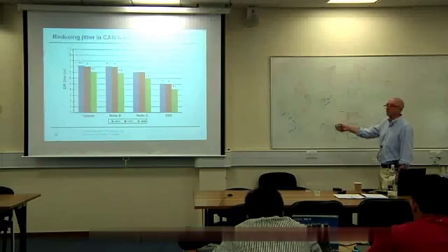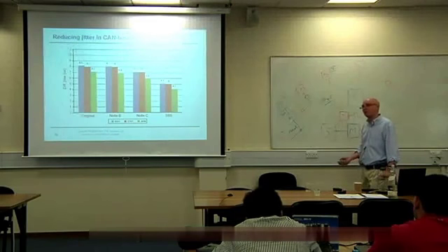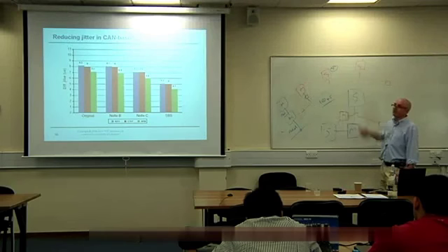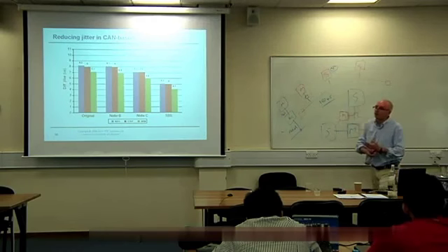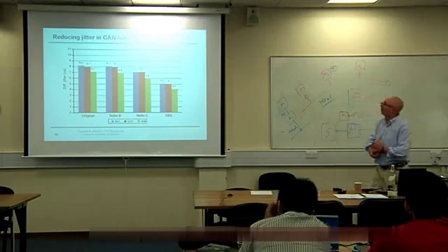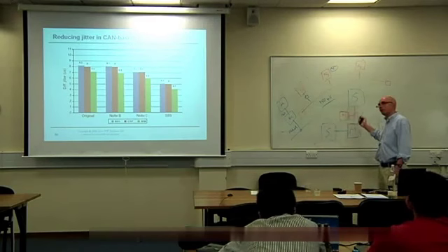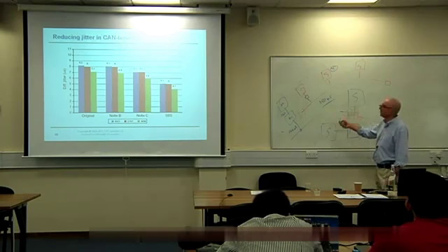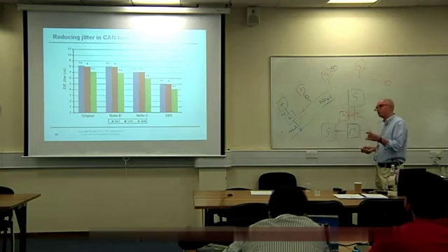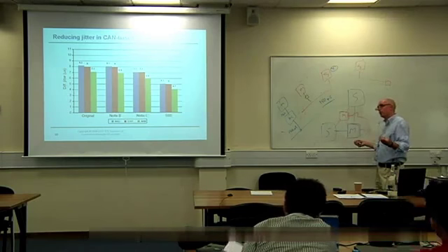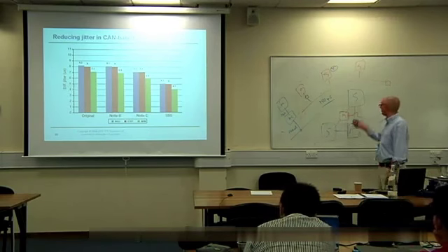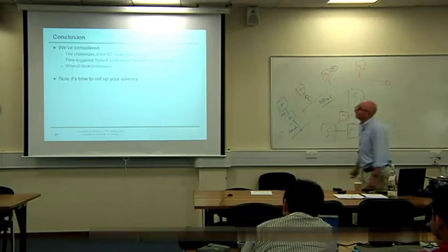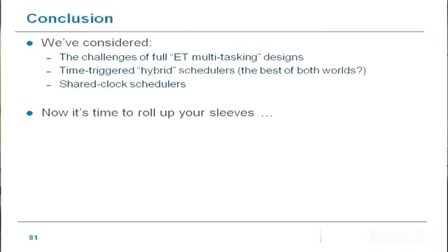People tend to assume everything is ideal and don't realize that, in fact, the level of timing variation they're getting from this is potentially quite significant. And even if it's not a shared clock design, even if it's any kind of message passing routine, and you've got 24 microseconds of variation in the message times, that might be significant, because you can't possibly get better resolution than that on the slave. That's where we're going to end for today.